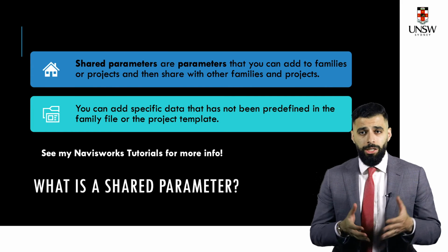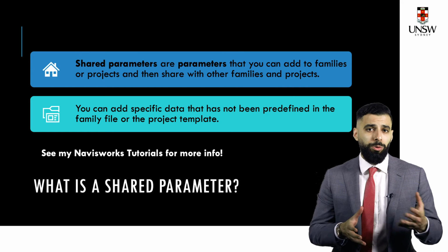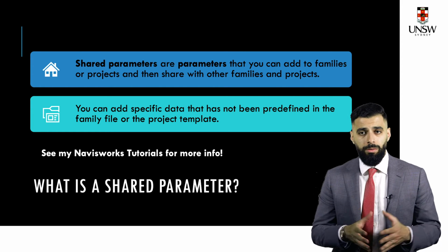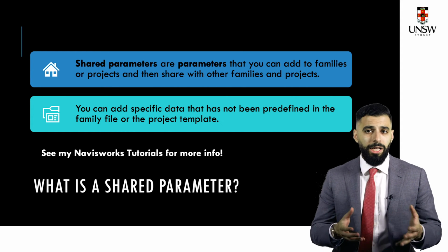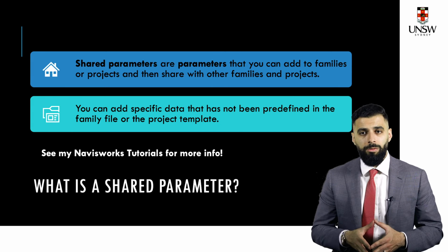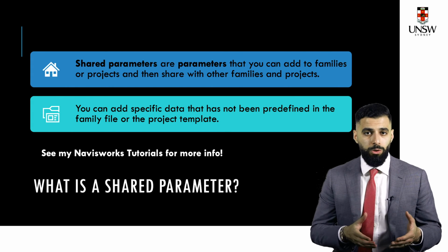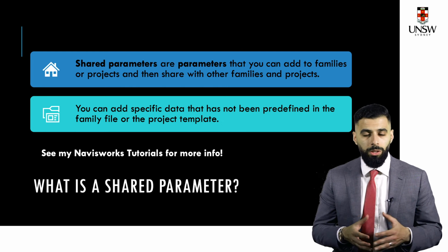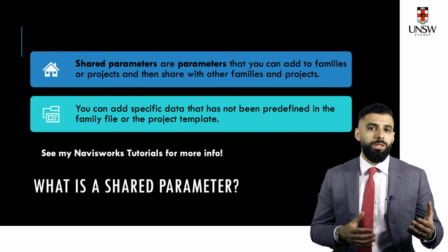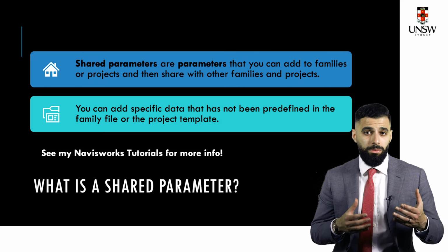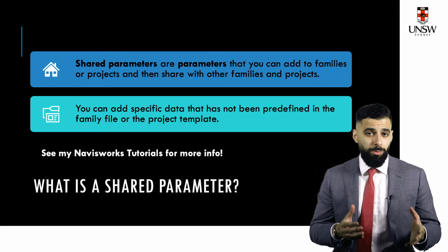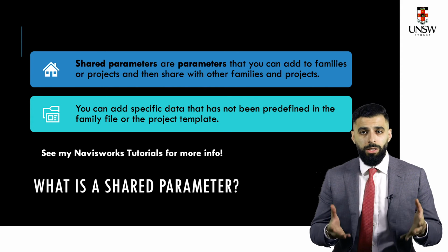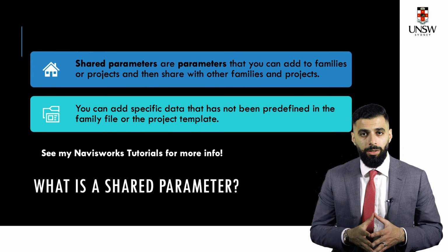You need to first associate each object in your BIM model with a shared parameter. A shared parameter is simply a field for you to insert data in, and the data can be anything that's associated with the specific family of objects that you have in BIM. In our case, based on the concrete slab example that I previously gave, you would need to create a shared parameter to insert information about each activity that the column is linked to in the construction schedule. Your construction schedule should already contain information about the workers needed, the tons of steel, and the area of formwork that's required, and also the volume of concrete that's needed. In addition to, of course, the precise number of workers that you have to have on that activity.